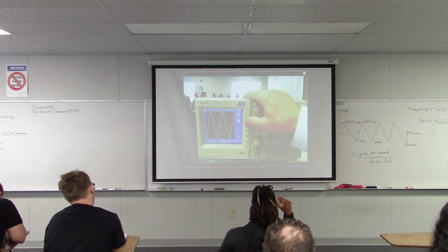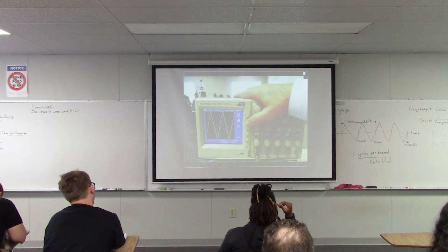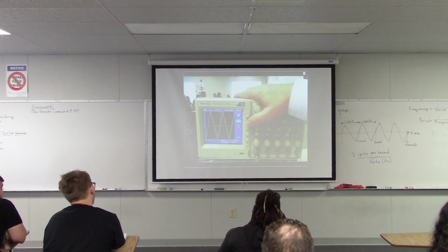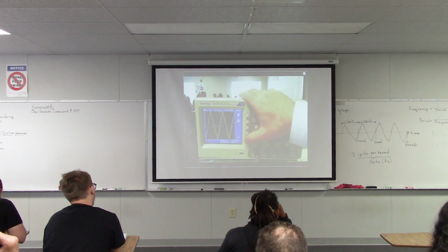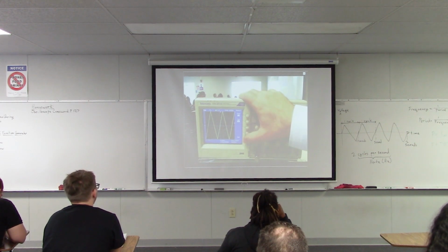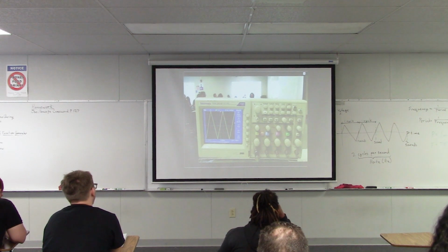And really there are many different types of measurements that you could choose. So there's frequency, period, mean, which is average, peak-to-peak amplitude, RMS, that's a different type of amplitude measurement, the minimum value, maximum value, rise time, fall time. So all of these different types of measurements that you could choose. You can just pick the one you like, and then when you are happy with it, you push back, and then it selects that and shows that on the screen.